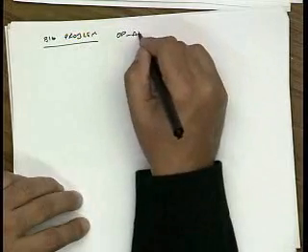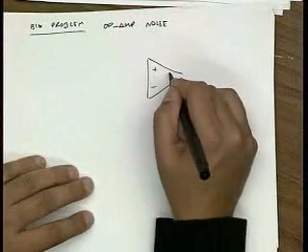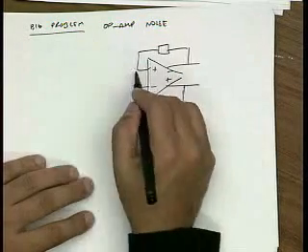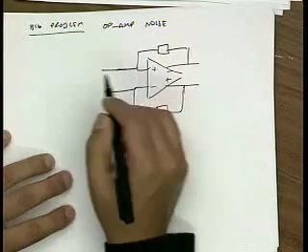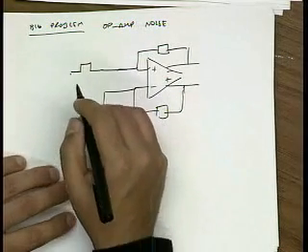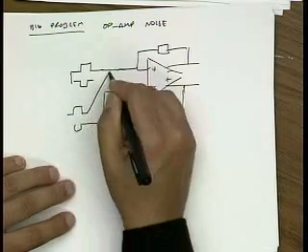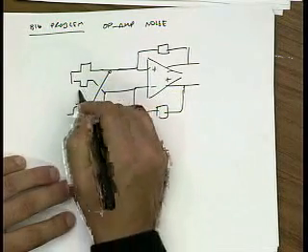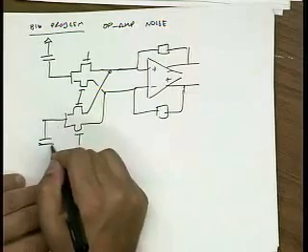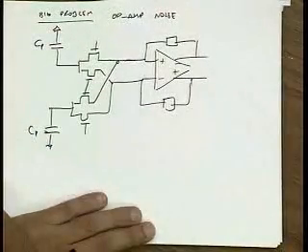There is one big problem with this circuit, and that's the op-amp noise. So let's see how that comes about. Okay, I have this op-amp, and it's driven by this time-varying circuit here. So let me bring this out like this. And naturally, there's some parasitic capacitance sitting here. Let's call that CP. There's always going to be some parasitic capacitance sitting here.